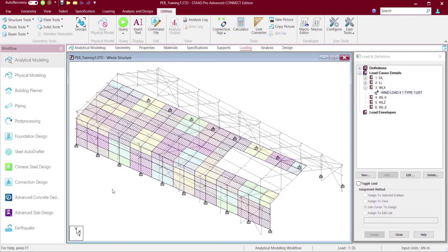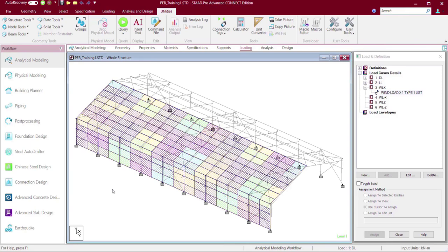Now, exactly, it is being applied on those panels, ignoring all those unnecessary geometries, members like bracings and all. You can see very neatly it has applied, and all those calculations, from the panel area, then intensity, then again it is fragmented into the nodal load, are done correctly in this case. So you can use this group option also for applying the wind load in addition to using them for the floor load.